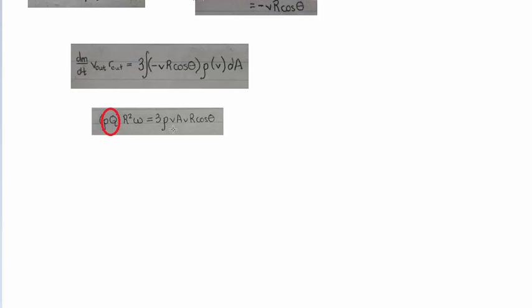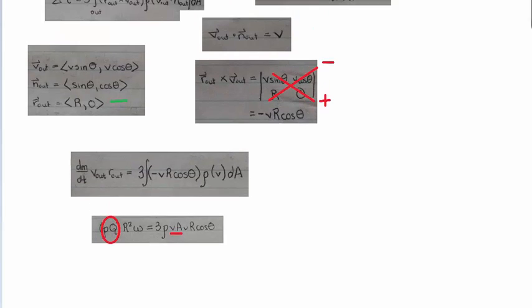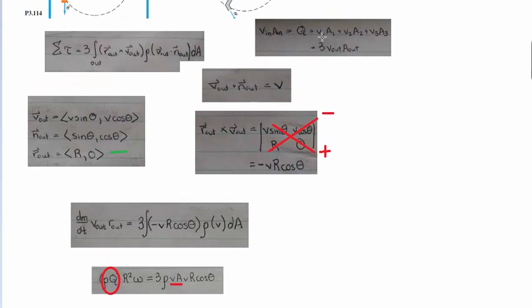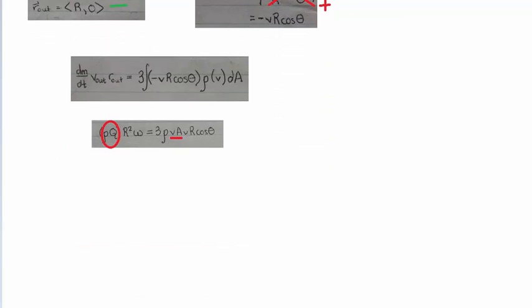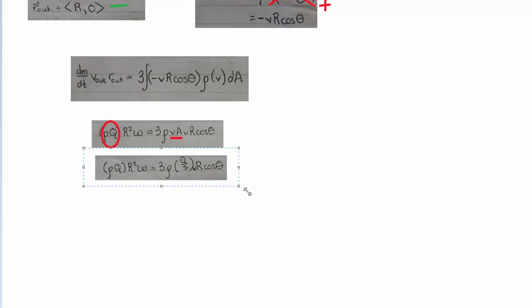But over here, with this VA term, just like before, because of our continuity equation, when we make the substitution, our V out, A out is actually just going to be Q over 3. Don't forget this, because this is how most people mess up the final problem. So we make that substitution over here, and this is what we get.